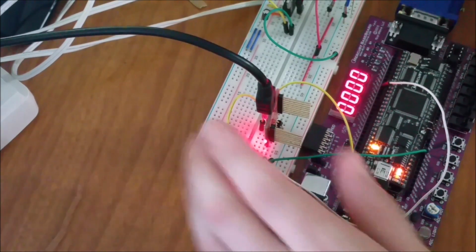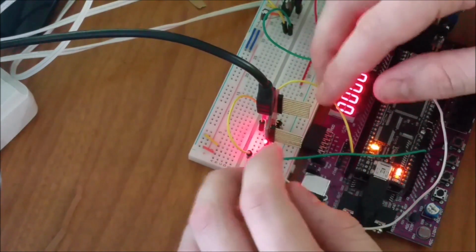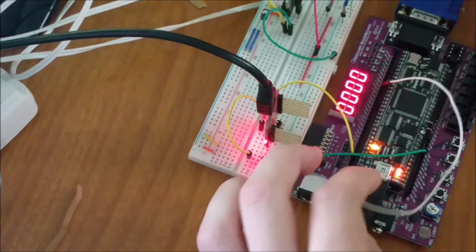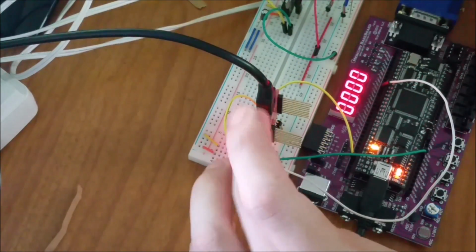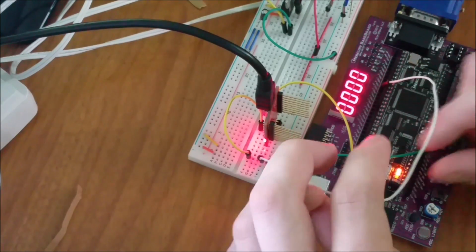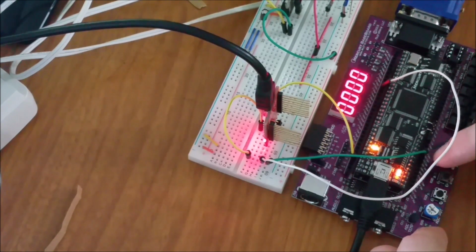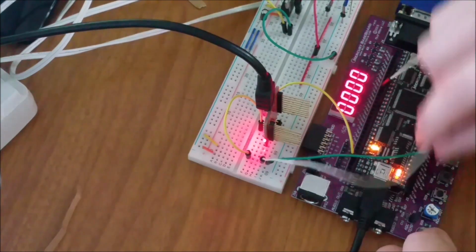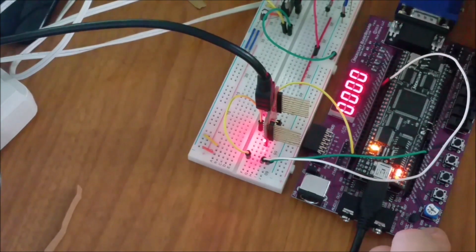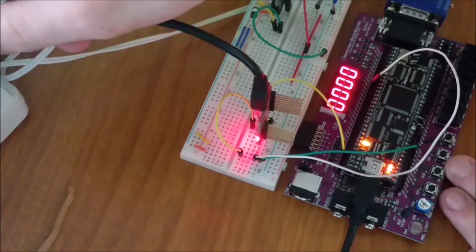So I got all the physical hardware set up. Here's the FTDI chip. It's on a breakout board provided by SparkFun. This yellow wire over here is a shared ground between the Mercury baseboard and the FTDI chip. Then the yellow over here just breaks out the TX pin coming from the FTDI and goes to the white and green wire. The green wire goes to the analog to digital converter chip on channel 5, and the white wire goes to PMOD 0. The white wire is the digital read to get displayed on the 7 segs. The FTDI is also powered through USB and connected to my computer right now.